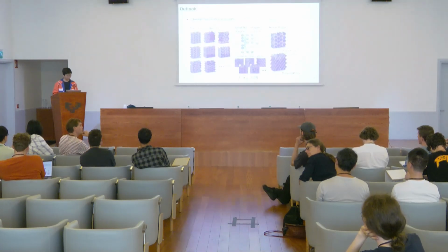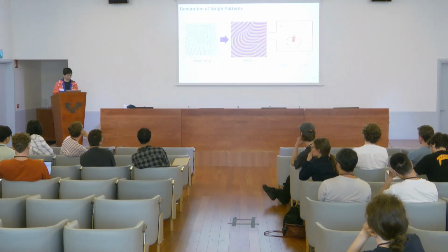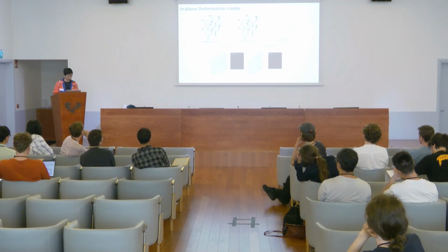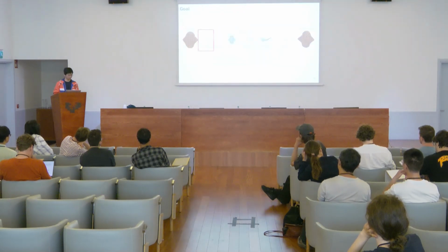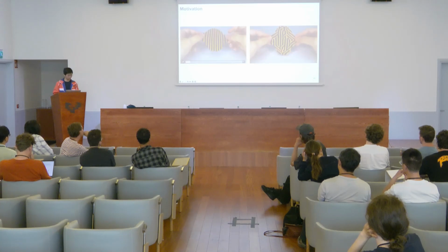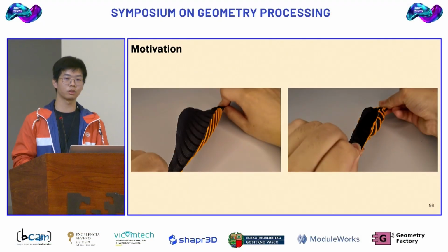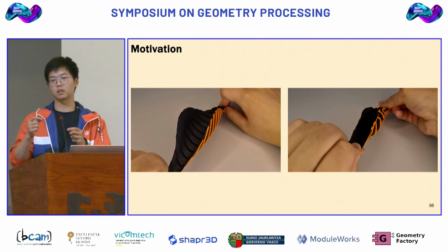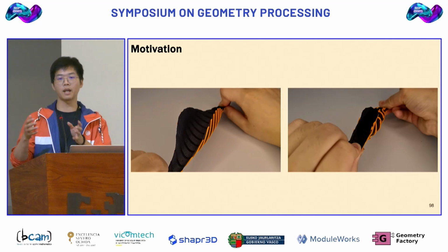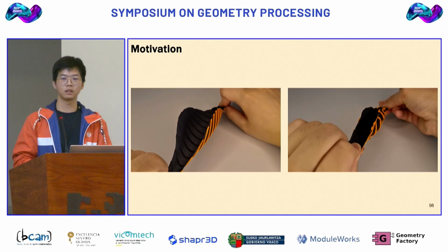Like in this one where you have these parallel strips, and then you pull in the X direction and it bends in the Y direction. And I thought that the optimized pattern would have some symmetry about the X, Y axis. You mean this one? Yeah. For this one, it should be symmetric, right? For the left one. But for the right one, because we optimize to a heterogeneous distribution, it will not be symmetric. And since we use simulation and numerical homogenization to characterize the macromechanical properties, the simulation might introduce a little bit of instability or the threshold for the convergence might introduce a little bit of asymmetry into the homogenized results. That is possible, yeah.